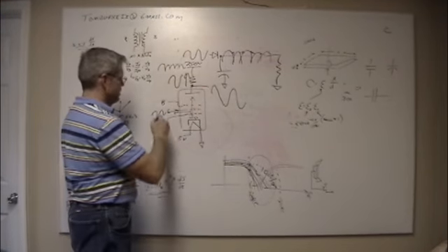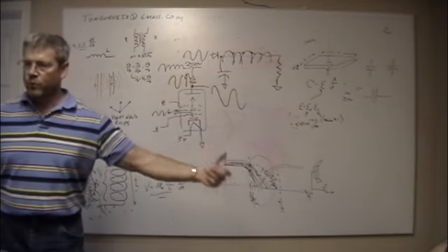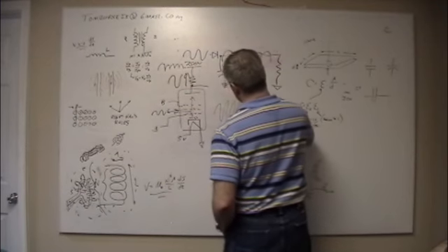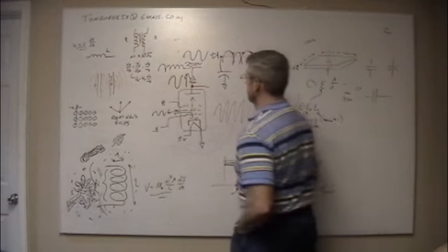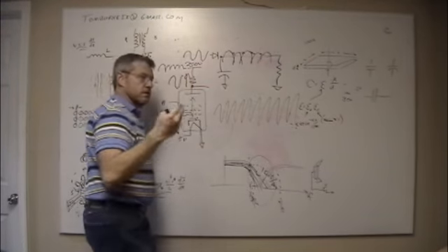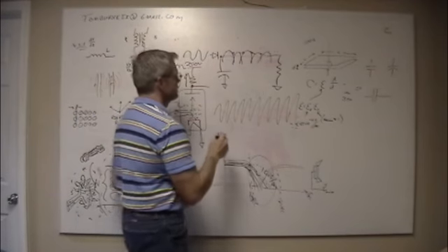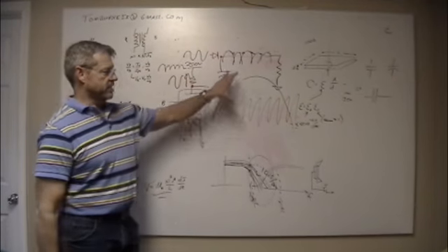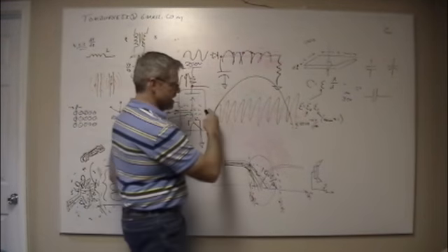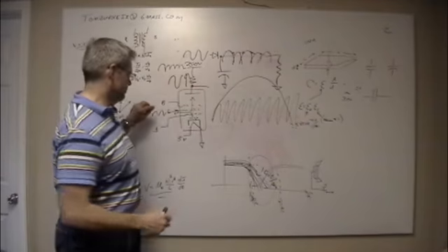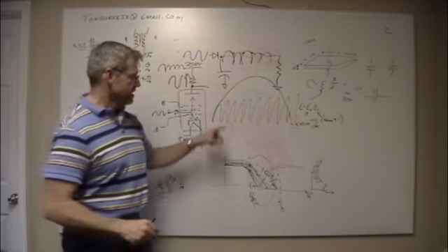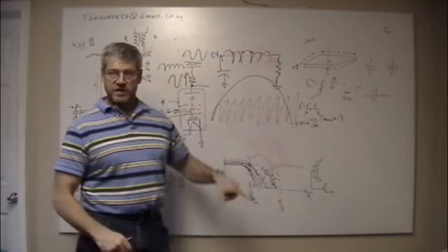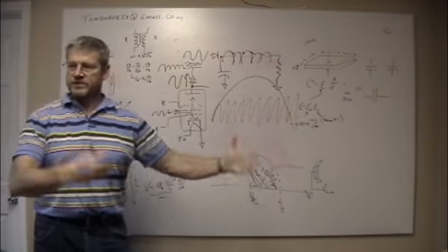now let's say I'm putting a 1 kilohertz tone out, right? So if this is a kilohertz, 4, 5, 6, 7, 8, 9, 10, and that's 120 hertz, that's doing that. So my tube's coming alive and it's dying, it's coming alive and it's dying. And I hear my sound, even if there's no sound at all, if I've grounded out the microphone input or the audio input, this thing's going to hum at 120 hertz. And as I start putting audio into it, you're going to hear the audio, but you're going to hear this god-awful loud tone on top of it. That's what you had.